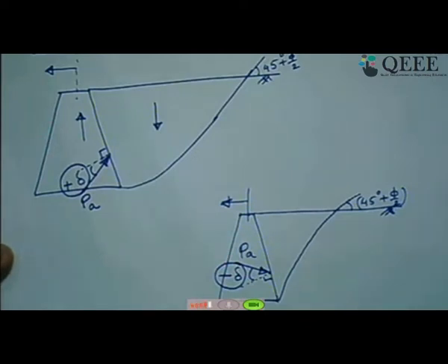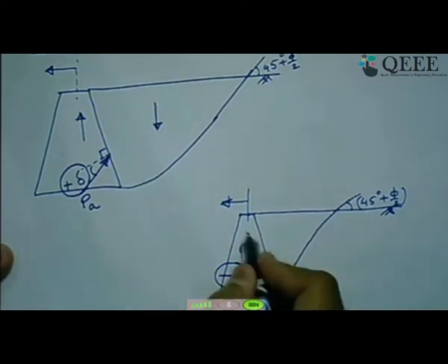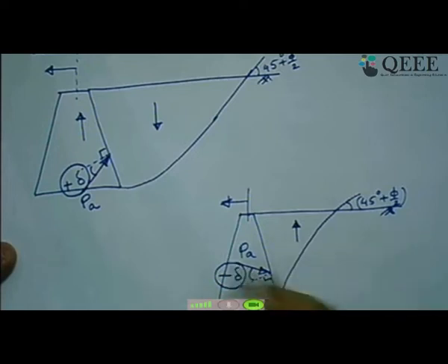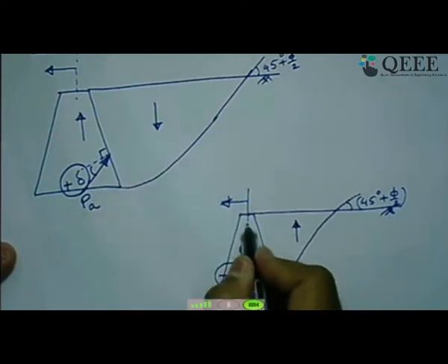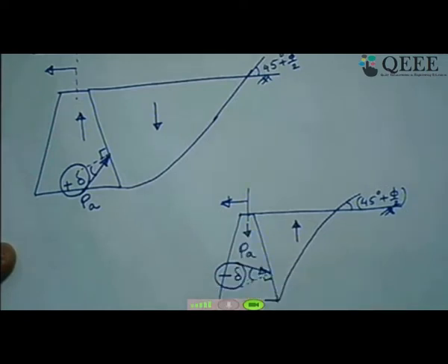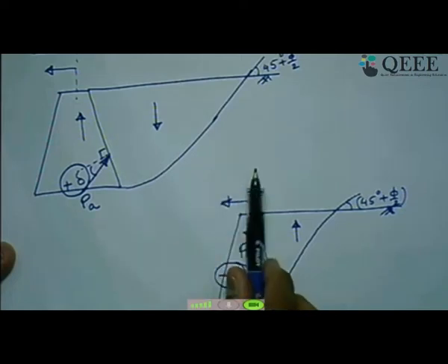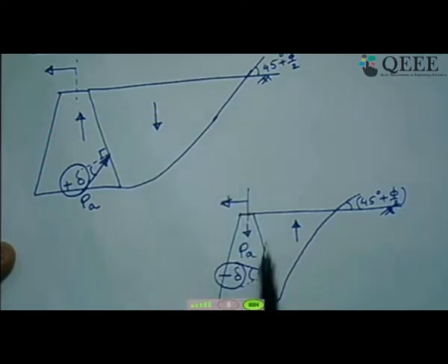Why does this kind of phenomenon occur? Let us understand. In this case, who goes up, who goes down? Here soil moves up relatively. All these are relative obviously with respect to each other, and wall moves down. When this kind of peculiar scenario occurs, as I said peculiar because this is not so common, this is more common. Why are we saying that this is still active? Because wall has moved away from the backfill. That's why it decides what type of earth pressure acts.